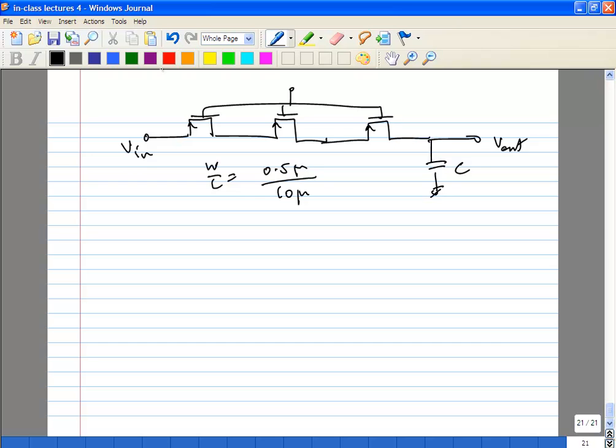Of course you want to use PMOSs, but you have to be careful. You'd be able to use PMOSs depending on where the input voltage is. Remember that PMOS can't pass voltages below its own threshold voltage, but that is not a problem here actually. The NMOS threshold voltage may be different, so you have to be careful.